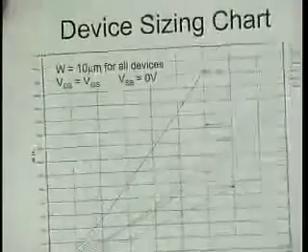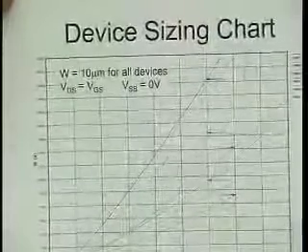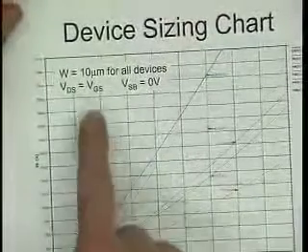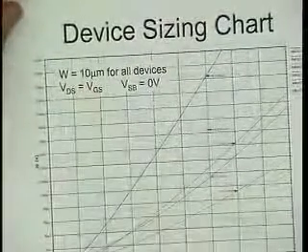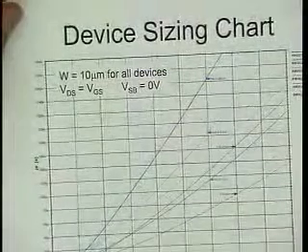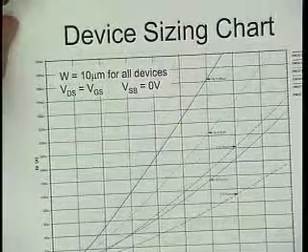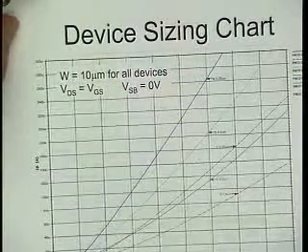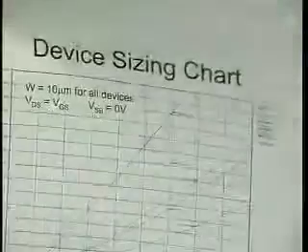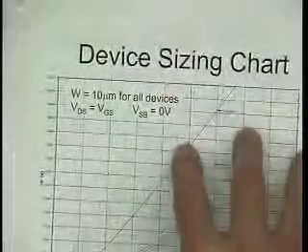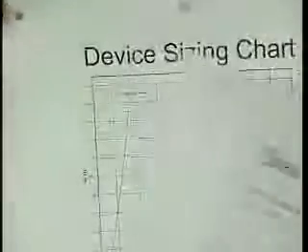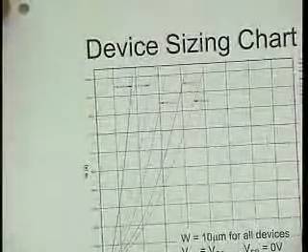The next two slides are graphs that I have run. I kept the W the same, but I chose different channel lengths, and then again V star here and an ID over there. And I use those in design. Here we have a bunch of shorter channel length transistors, and here a bunch of longer channel length transistors, and you can run these yourselves also.